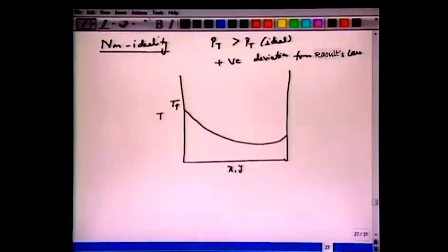Now we have TB and we have TA, and the bubble point curve reaches a minimum before it increases to this TA, and we plot the dew point, then we have a curve like this. So notice here, if we have this composition mixture of ZF as a feed, and if we heat it, then the entire liquid will be converted into vapor without any separations.